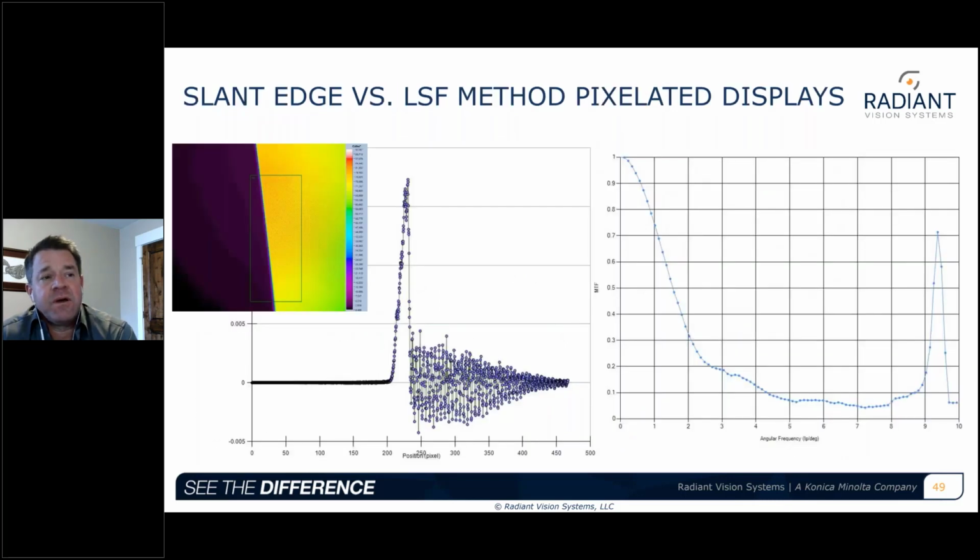As a note, although high resolution is desirable for an XR test system, there are factors to consider. An MTF measurement by a high-res camera can unintentionally resolve the display pixels, measuring contrast between the pixel separation and thus impacting the final MTF result. Shown here, the LSF of the slanted edge MTF calculation is confused by the pixelation of the display that the camera sees as contrasting elements. Note the pixelation plotted in the LSF chart to the left and the false MTF peak that results in the chart to the right.